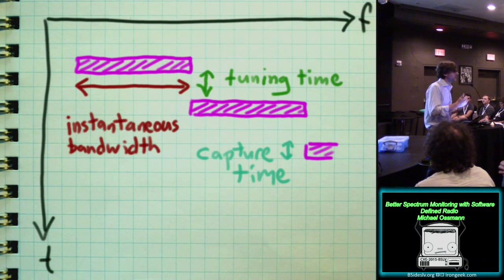Calibrating the power level is another problem, and you probably have to go through some active step to calibrate your equipment and see, oh, this one picks things up at this frequency 1 dB hotter than this other device does. So you have to come up with some calibration measurements and use them to normalize your data in some way. You have to deal with calibration of power levels, time, and frequency. So those are excellent points.